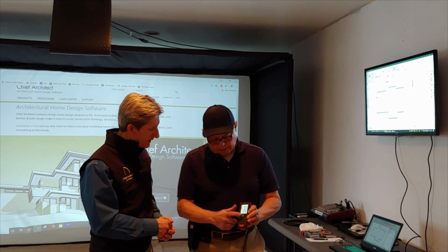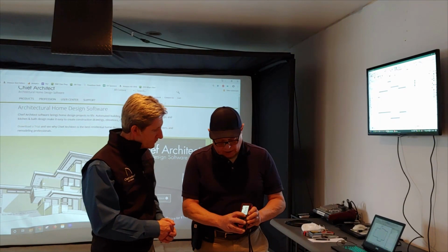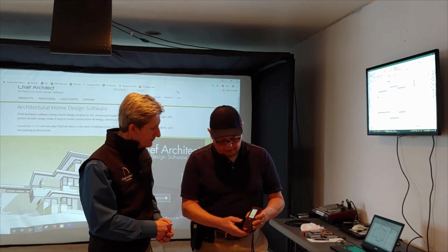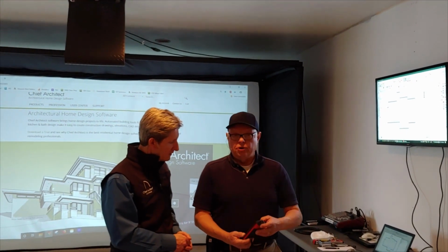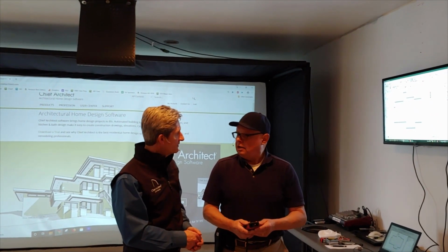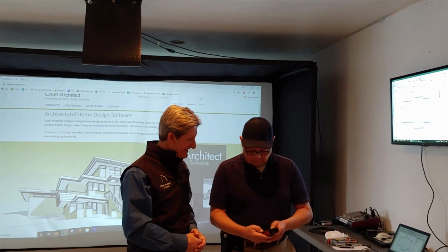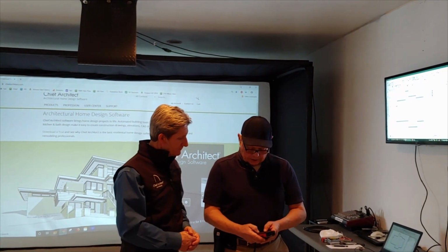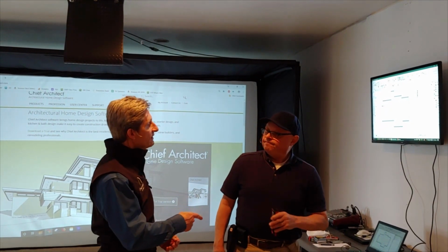And there's a couple of buttons here on the Leica, and this one accesses the memory. So if I hit this, then I can run through the memory stack. Okay, and I said it was 64, actually it's 30. Made a mistake there, but still, that's a lot of measurements. You have to have that memorized. Well, that's why I don't do too many of them. But I can toggle through these and get each one as it's going down. And when I'm done, I just hit the button again, and the display comes back. And then you go over and type them in.